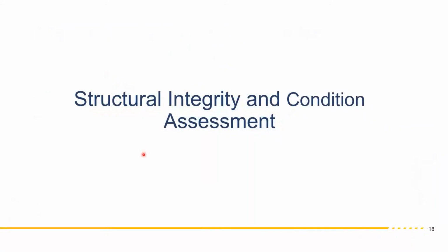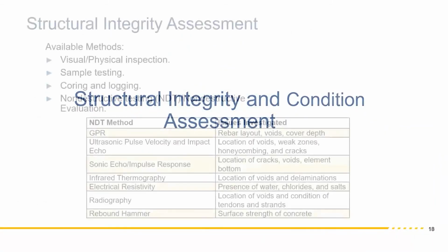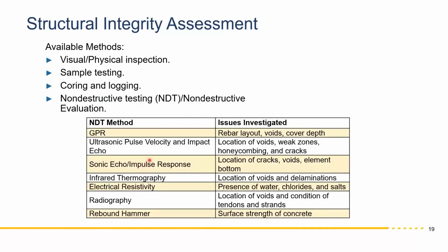So I'm now going to shift gear and talk about structural integrity assessments, and that typically involves a lot of NDT. I already talked about GPR and impact echo and UPV, and Bernie talked about sonic echo and impulse response and parallel seismic and use of gradiometries in boreholes. I'm going to talk about different aspects of structural integrity using geophysical logging.